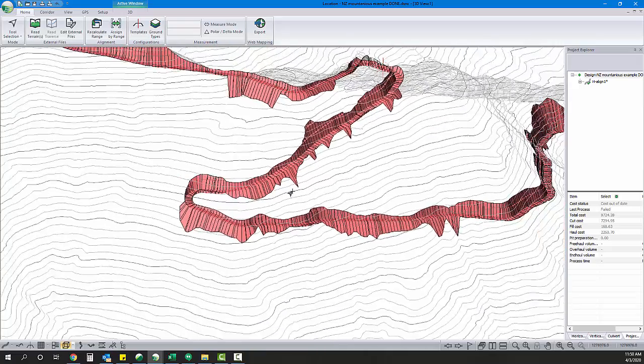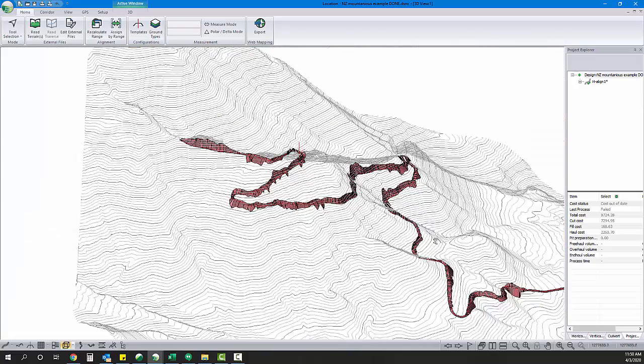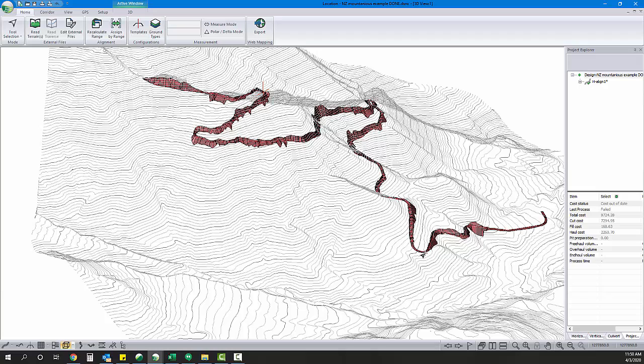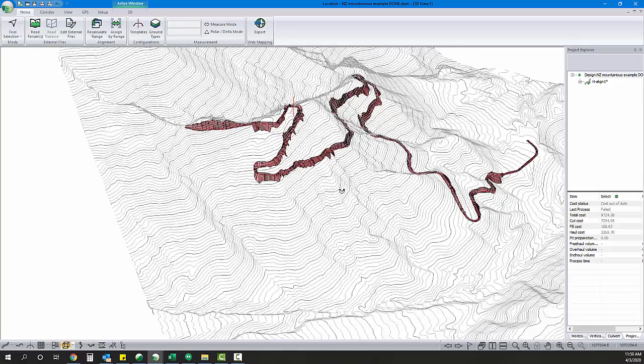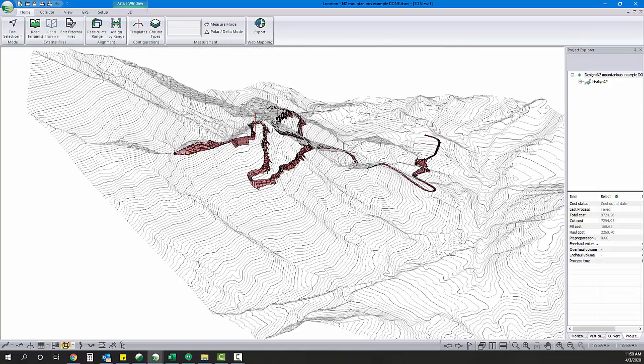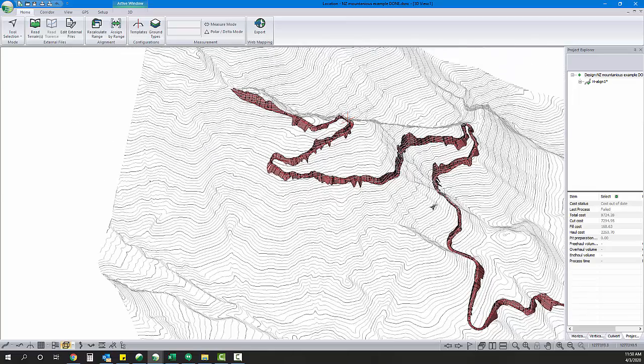Of course, general road design practice for designing switchbacks is you always want to work with the terrain and find ideally a flat-ish spot to put your switchbacks. So these aren't by any means flat, but we're making the best opportunities out of the section of ground that we have.